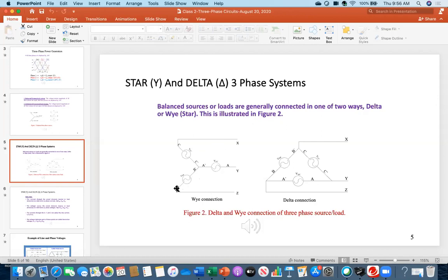In case something happens in one three-phase system, power flow still continues with the help of the other three-phase system. That's why typically you might see 8 cables. Those are not the delta connection. Those are typically the Y connection. There are relative advantages and disadvantages. As I said, you can connect the neutral wire here, so in that sense, you have flexibility to use it.